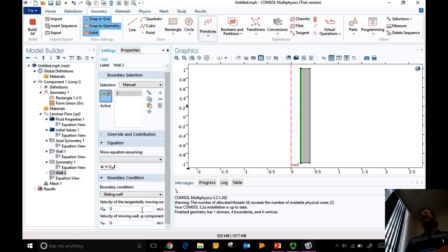And those can be discovered from a fundamental sense by MD simulations, molecular dynamic simulations. But on a macroscopic observation, you just discover their presence by looking at macroscopic flow rate versus pressure drop relationship. Okay? Any questions?